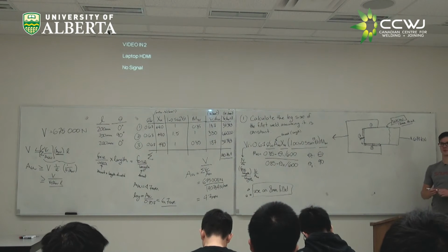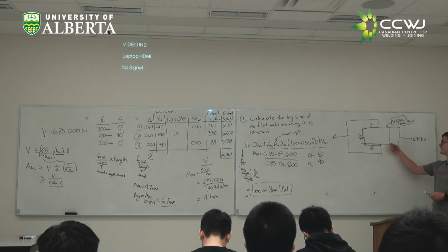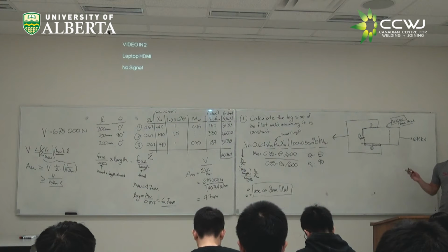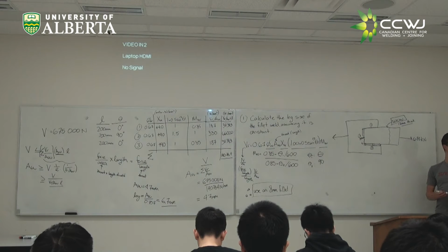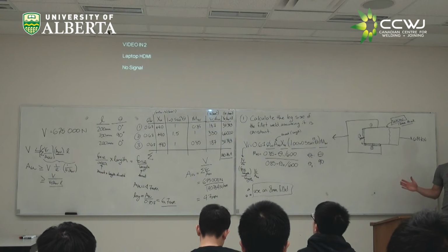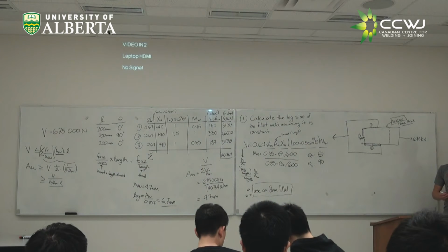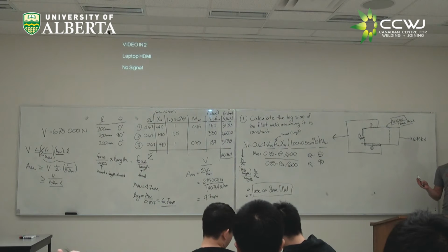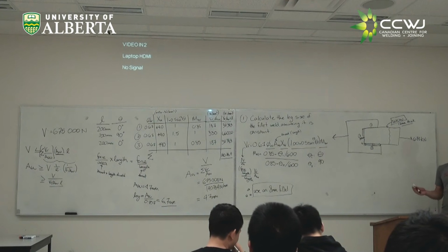But I think the formulas from last class, does anyone remember what I'm talking about? There's a formula to check to make sure that we're not going to fail in our base material. It's interesting because that's not really a welding problem at that point. That's just a design problem. Those formulas are something we could have done probably after I think all of you guys have taken Civi 270 or something equivalent. That's a really easy computation. That's an area, that's a force, you get a stress, you compare that to the failure stress of your material, and you know whether or not you're going to be fine. The only thing we've done a little bit differently in this class is we actually then looked at what the design code is going to tell us is the failure stress of our material.